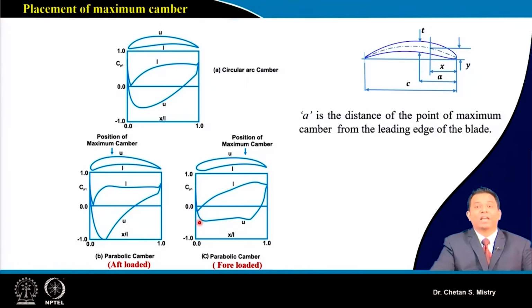I will be having a little acceleration, but that will be followed by constant pressure, and then deceleration. That's what is happening on the later part of my blade. And in the same way on my lower surface, or pressure surface, I will be having flow acceleration followed by deceleration of my flow.